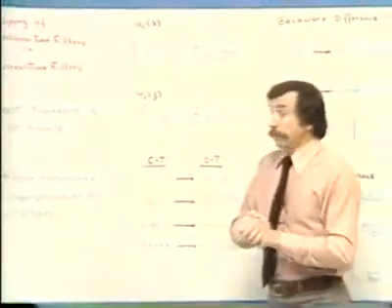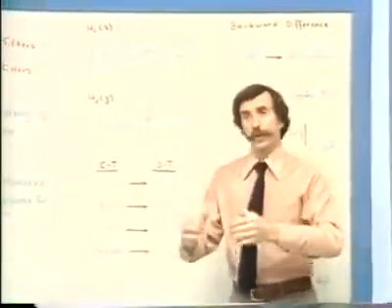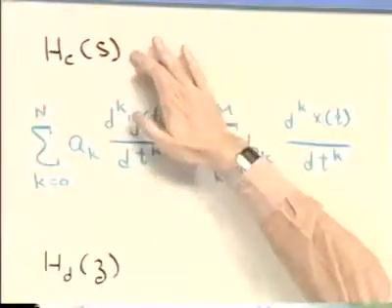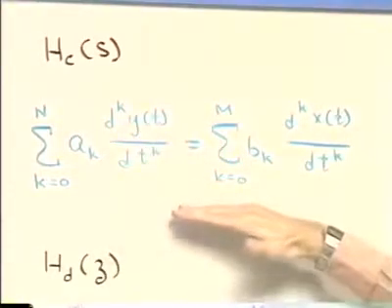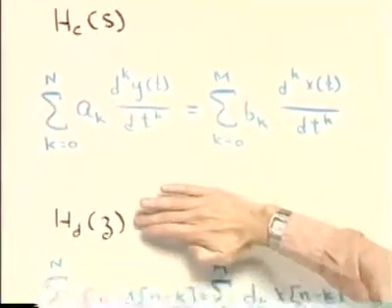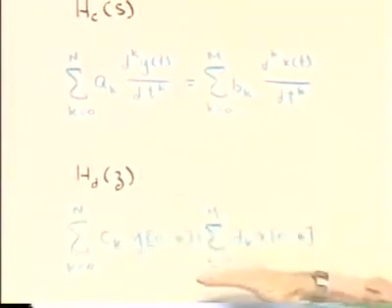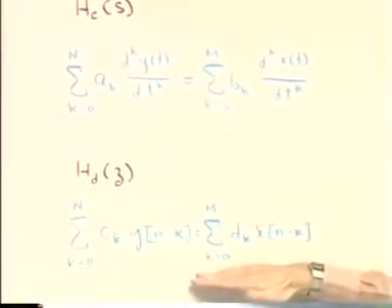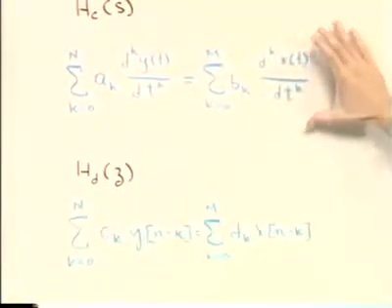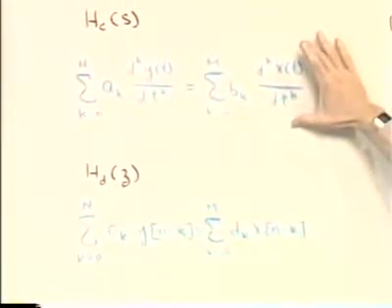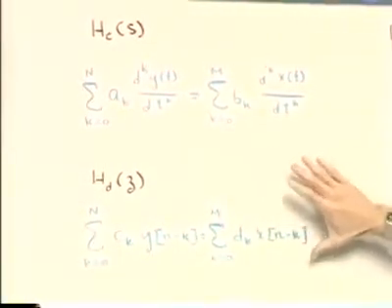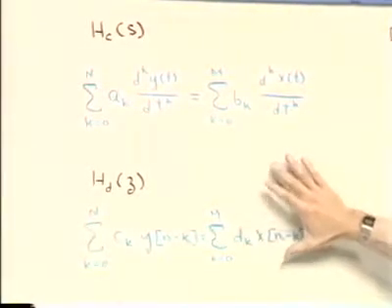All right, now if we want to map continuous time filters to discrete time filters, then in continuous time we're talking about a system function and an associated differential equation. And in discrete time, there is the corresponding system function and the corresponding difference equation. And basically what we want to do is generate from a continuous time system in some way a discrete time system that meets an associated set of desired specifications.